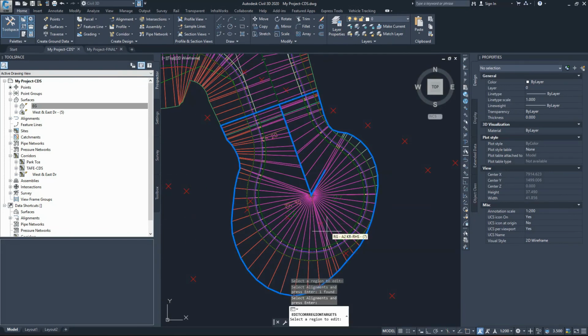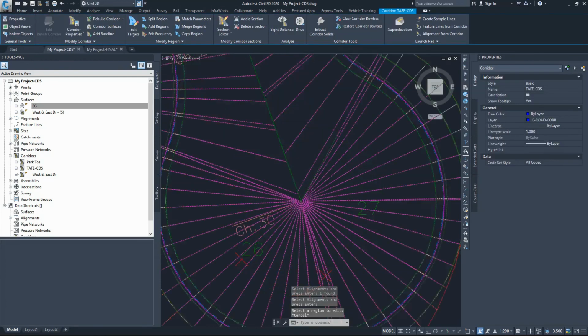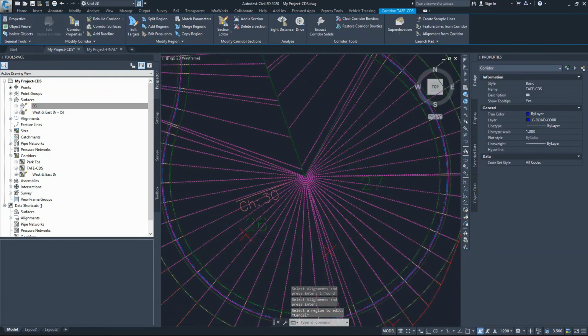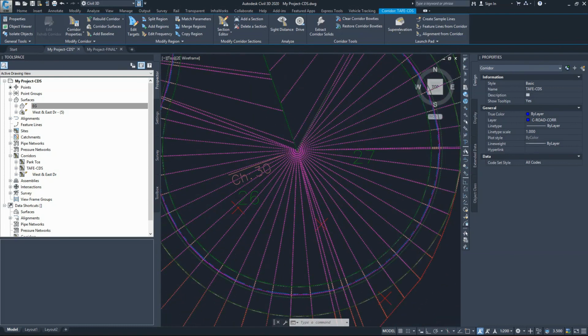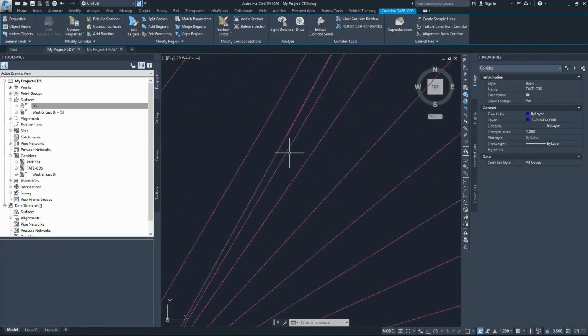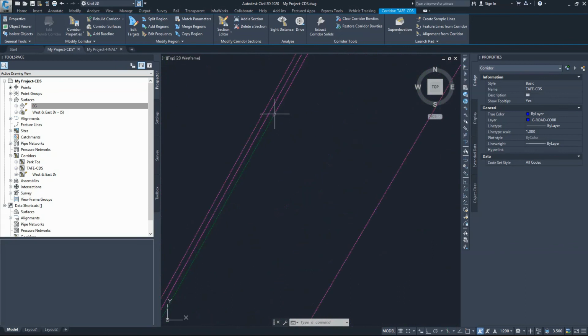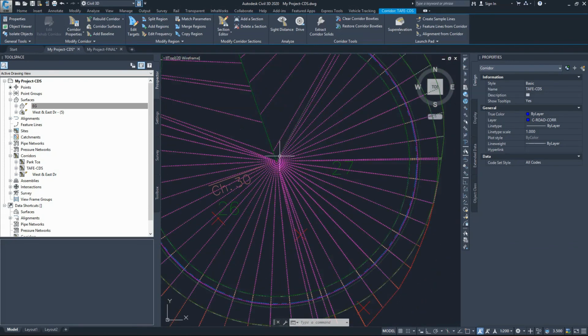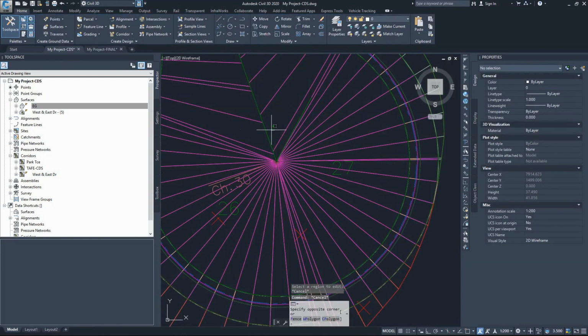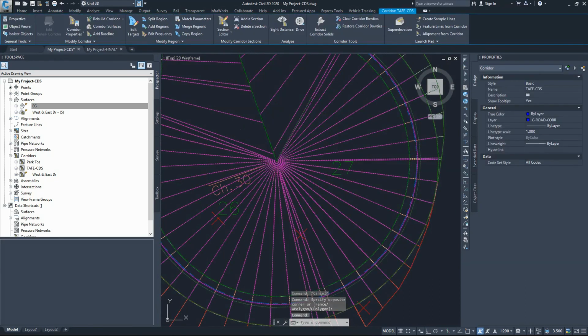Okay, so that's the design done for the Cul De Sac roughly. Now if you look at that, you have that small green line here. Simply that's an area where it doesn't have targets because you've got some cross sections, for example this cross section here, that doesn't reach that alignment. So if you have small areas, I'll just exaggerate that error a bit for you so you can see.